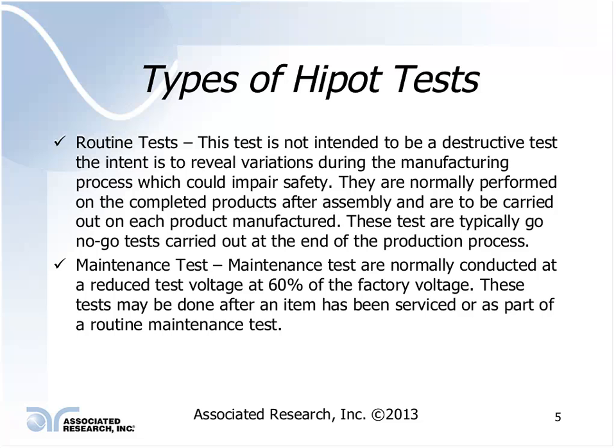Part of the reason for this is if the product has been working, you just want to verify that the insulation is good. You don't want to overstress it to the point where you could possibly cause damage to the insulation. But you do want to weed out anything that might cause a potential shock hazard to the individual that may be using the product. Face it, that's the whole purpose of the Hipot test, is to find these types of problems.